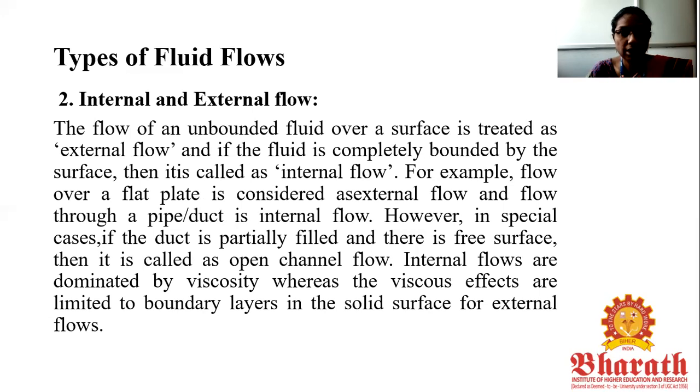However, in special cases, if the duct is partially filled and there is a free surface, then it is called open channel flow. Internal flows are dominated by viscosity, whereas the viscous effects are limited to boundary layers on the solid surface for external flows. So this is about internal and external flow. The best example of internal flow is flow in a pipe or duct, and external flow is fluid flow over a flat plate.